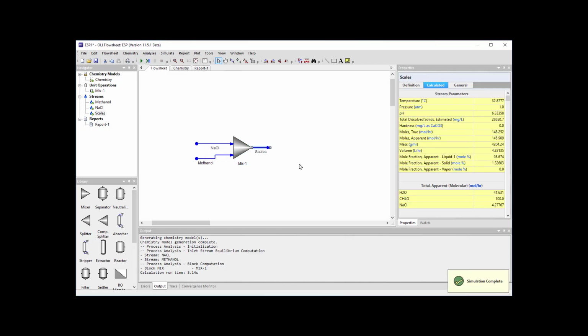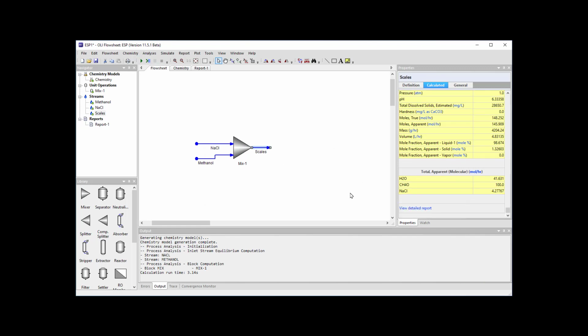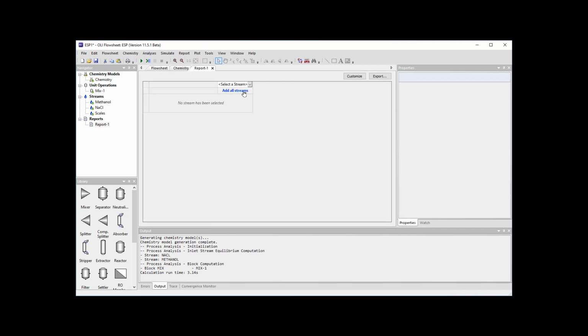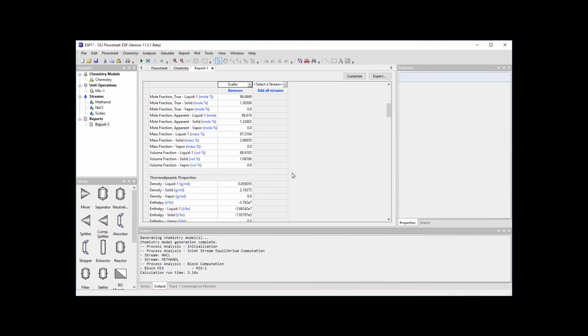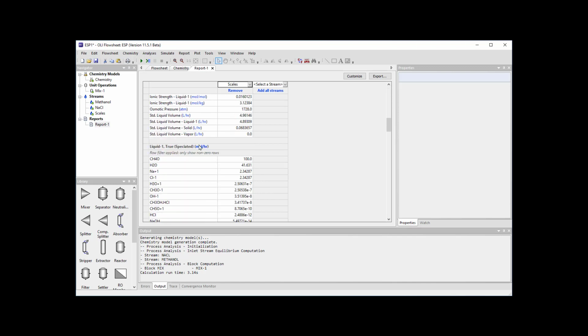We look at the output here and scales. That's the name of this unit, and we can get the units here. Again, they're not in our units because we created the object. I can go in and look at the stream itself here, and go down and look here. Again, we have to change the units. Had I started in those units, I would have had them throughout every single object. Now I have to go back and change all the ones I've already created.